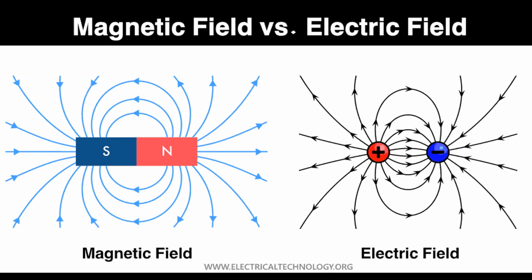In summary, an alternator converts mechanical energy from the engine's rotation into electrical energy by inducing alternating current in the stator coils. This AC is then rectified into direct current, regulated, and used to charge the battery and power the vehicle's electrical systems.